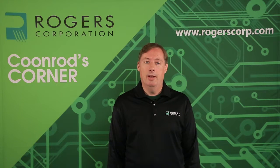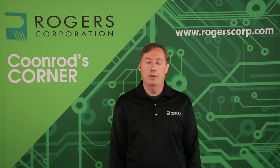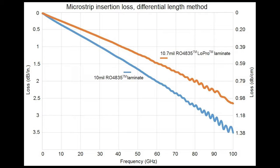But now I'd kind of like to look at an insertion loss curve that compares the standard product to the LoPro product when using 10 mil RO4835. The insertion loss curve that I have shown here is generated by making 50 ohm microstrip transmission lines using differential length method, and you can see that I have losses that are pretty well behaved all the way out to almost 100 gigahertz. And for this particular material, the 10 mil 4835, it is used actually in some situations at 60 gigahertz for some of the new backhaul applications. And at 60 gigahertz, the standard product, which is again 10 mil RO4835 laminate, there's about 2 dB per inch loss at 60 gigahertz, and that's considered very low loss.